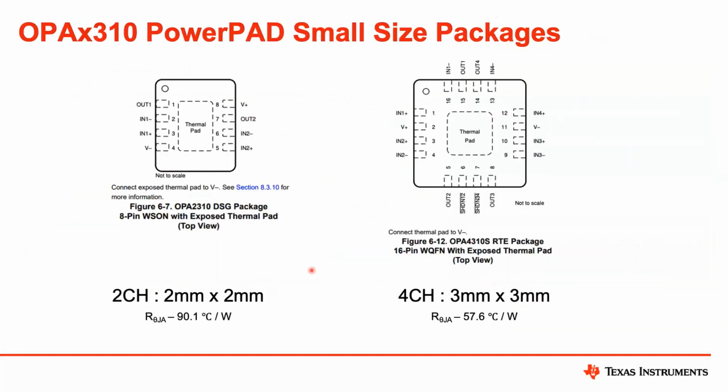Finally, the two packages that we have for the 2310 that have power pads are the DSG package and RTE. We understand that some customers might be a little concerned with having such a small device driving a lot of output current, and that's why we have these packages available, so that they have a thermal pad to help cool the device down and prevent any heating. All right, I'll turn it over to you, Bhuvanesh.